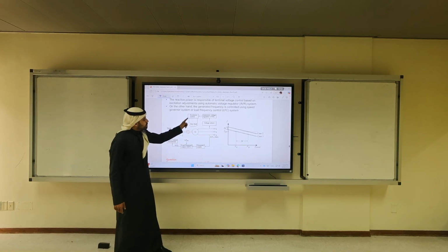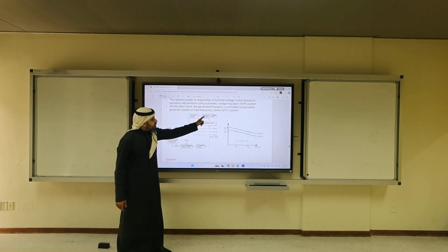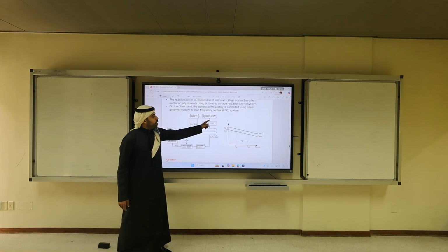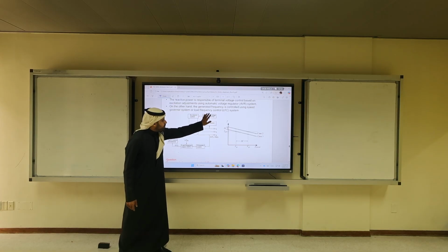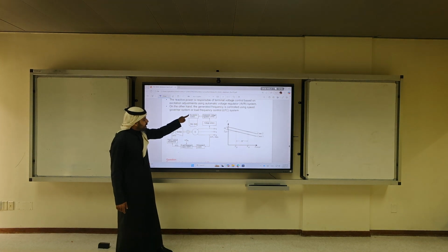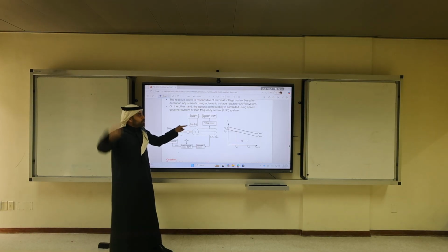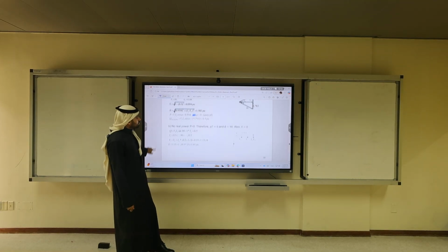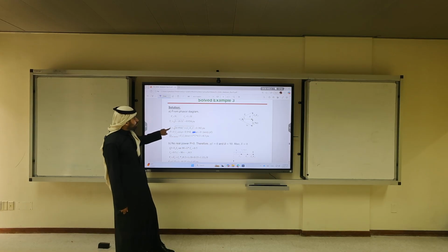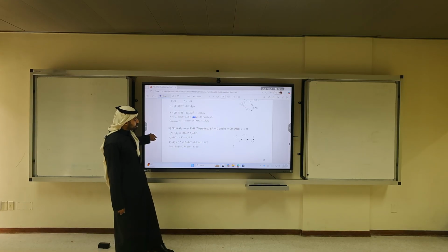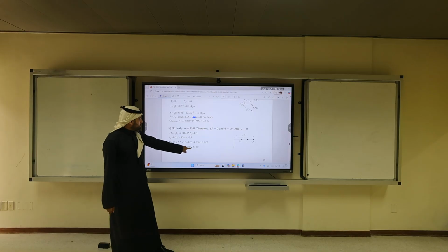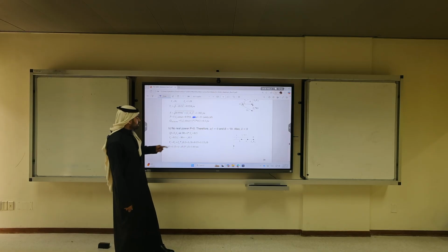The upper system is what we call the automatic voltage regulator, the AVR. It's in the homework. We get the voltage measurements, we put them into this AVR, its controller. It goes to the exciter and it increases the field current, and then we can increase E. For example, in part B, we had to increase E from 1.382 to what? To 1.65 in part B. How did we increase this?